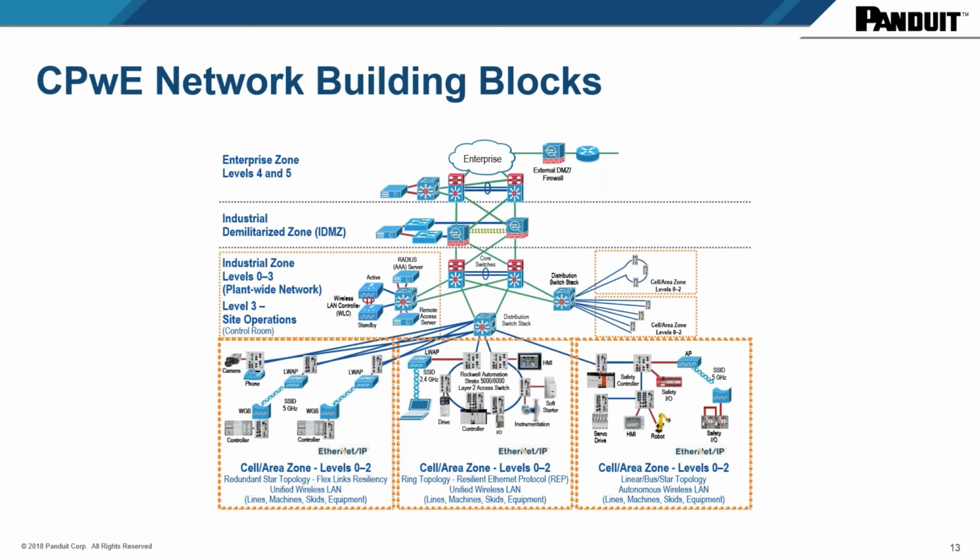So when you look at level 1 in this architecture, you find different cell areas. Each one of those cell areas is independent and runs totally autonomous, but the data that's shared from cell area 1 to cell area 2 has to be shared across very dedicated lines. In this architecture, you'll see that there is a point where we have a distribution switch, collecting all the input coming in from cell areas 1, 2, and 3.